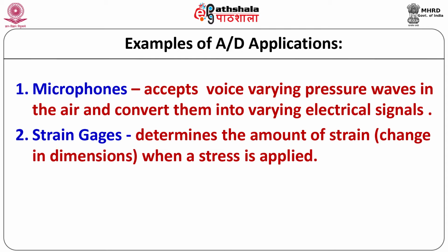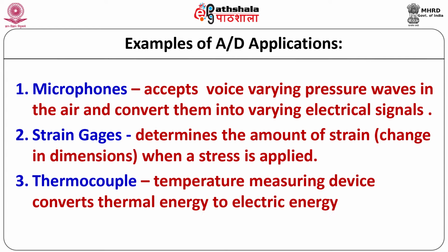Another example where we require an AD converter is use of thermocouple for temperature measurement. As we know, the output of thermocouple is an analog one. If we want to convert the output of a thermocouple into digital form through some signal processing and using AD converter, we can convert output of a thermocouple into digital form.